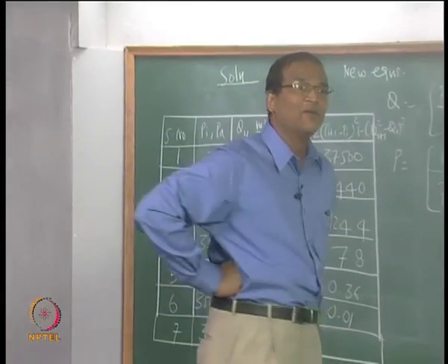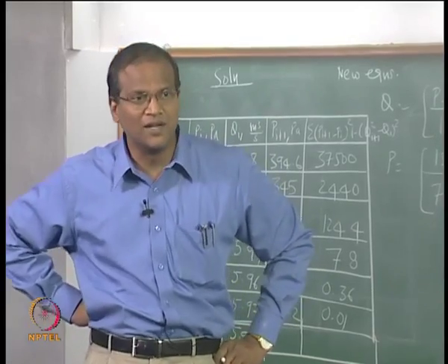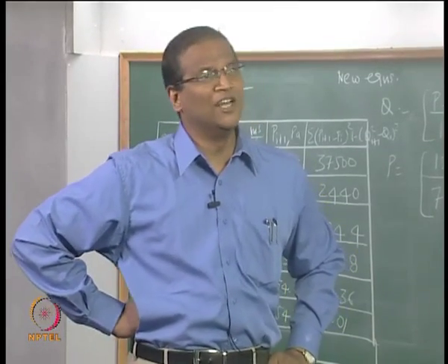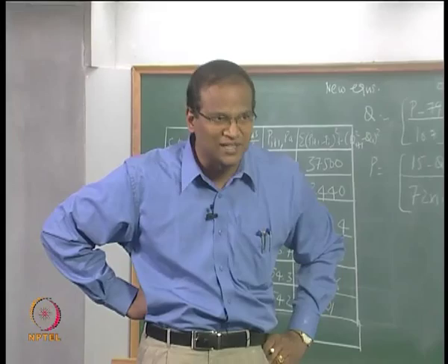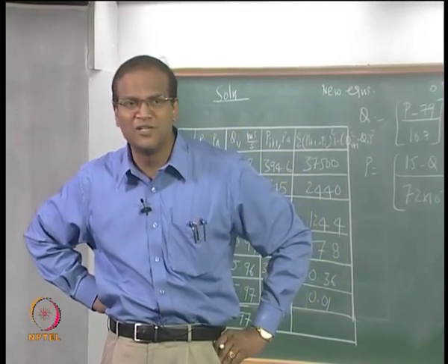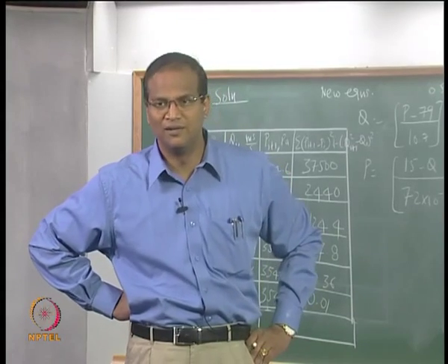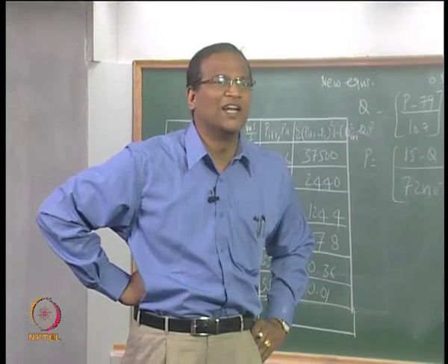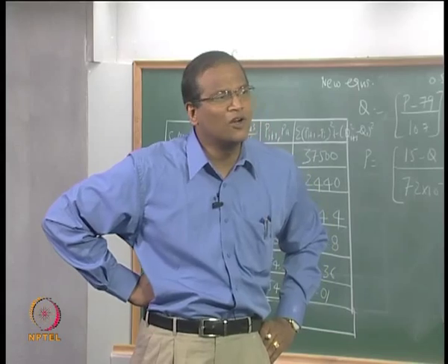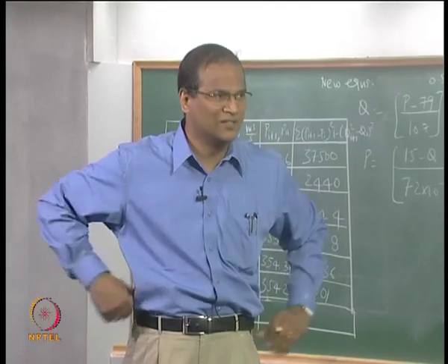That means you have an instrument which can resolve that. Therefore, when you have an instrument which can resolve only 0.1 degree centigrade, you take the temperature measurements repeatedly. Once you get 36.5, once you get 36.4, once you get 36.2 and all that, and you take 10 or 15 readings and average, we should not write the average as 36.546.